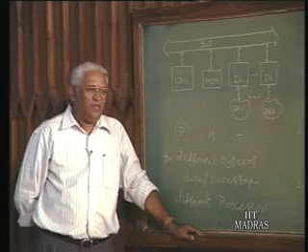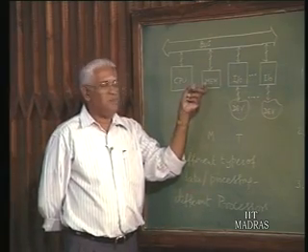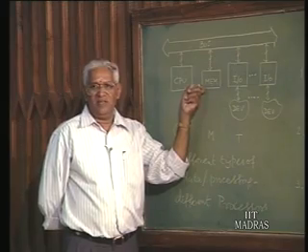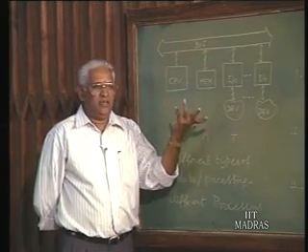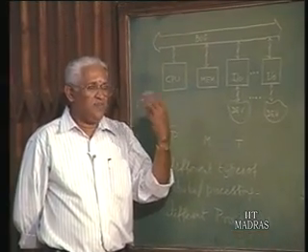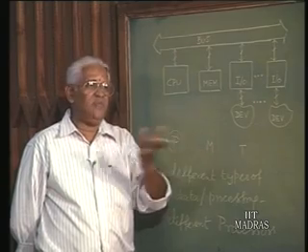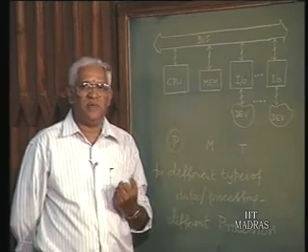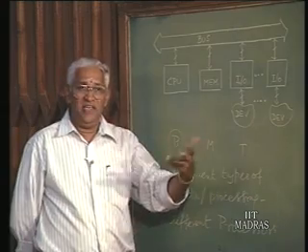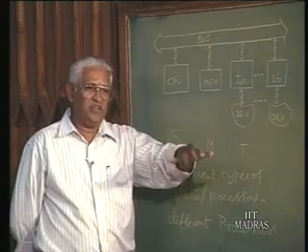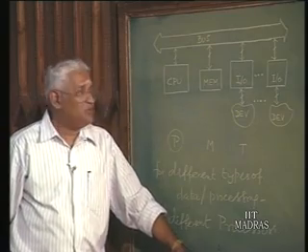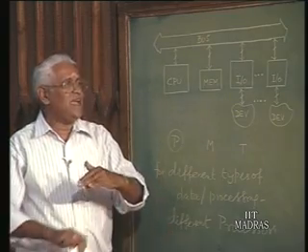Why? Because instruction and data both go from the memory, and once when a data is being processed, it is possible to fetch the next instruction and keep it ready, which generally we refer to as pipelining. Keep it ready in anticipation that it is the next instruction that will be used. It may or may not be used. So, you parallelize the activity, right?